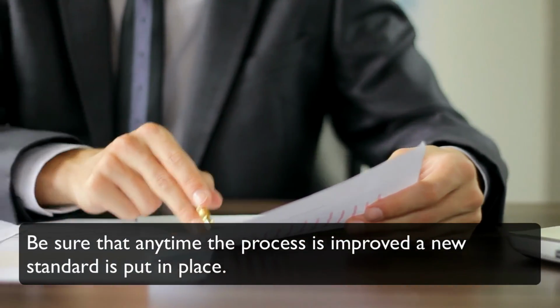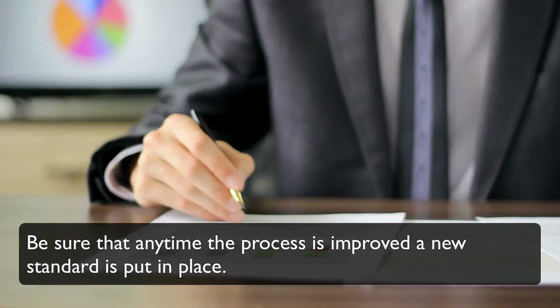Once the setup is locked in and repeatable, you can then begin to look at the setup from a more granular perspective. As you do this, you will find areas where seconds can be shaved and work can become easier. Be sure that anytime the process is improved, a new standard is put in place. Remember too, you have a Gemba walk, video, and a value stream map that can be left at the point of use and updated in real time. As inspiration hits, act on it and keep on improving while you reduce that setup and change over time.